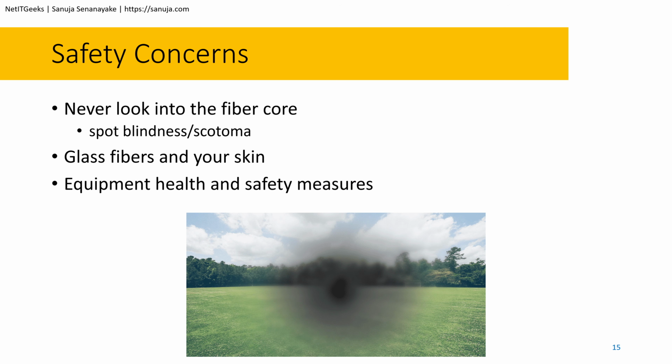Even if you're just simply laying a cable on the ground or simply plugging in a cable, I would recommend that you actually use the safety glasses. And for your skin protection, you can use these glass fiber rated gloves that will protect your hand. If you ever get those glass fibers inside your skin, you can use tweezers to try to get them out. And if you still feel there are maybe glass fibers inside under your skin, you need to seek medical attention as soon as possible, because that could create medical complications down the road if you just leave that fiber inside your skin.